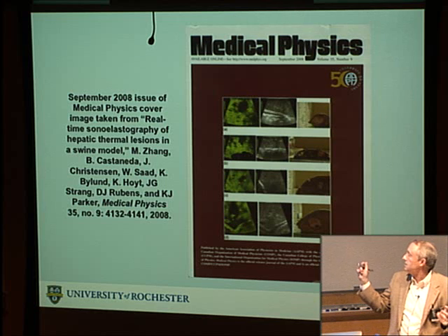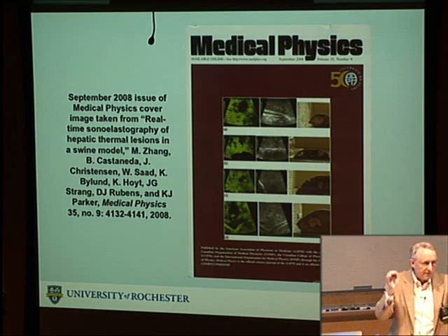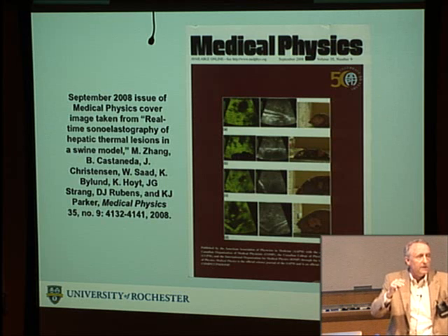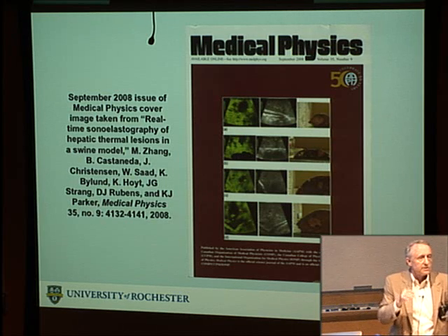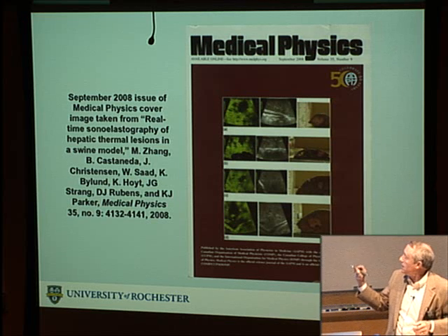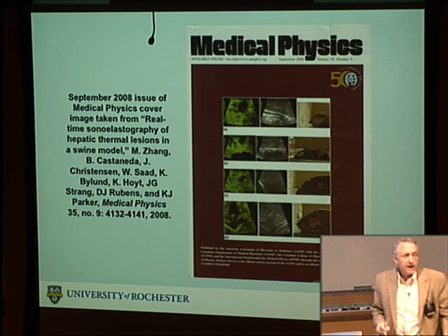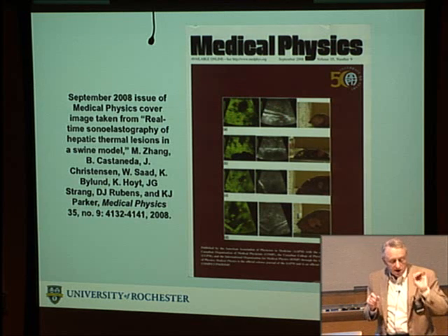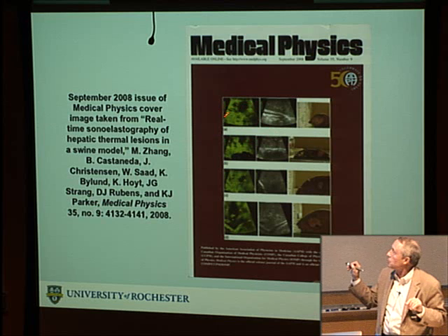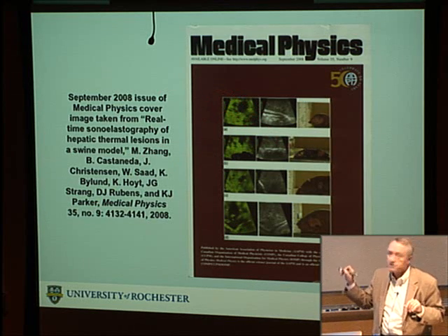So the green is signal processing that's tuned for sinusoidal steady-state vibration at 100 hertz, the shear wave signal at 100 hertz. I should say the Doppler signal from that. So this is a special Doppler signal processing as well, basically. And if you have a strong arterial pulse, that'll still show up with some interference. But basically, we've switched the signal processing over here.